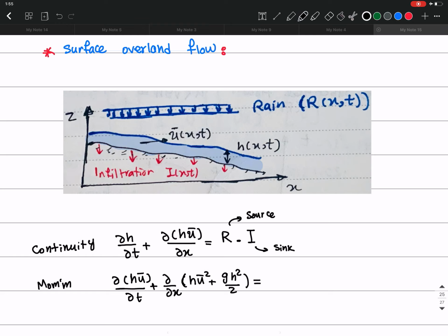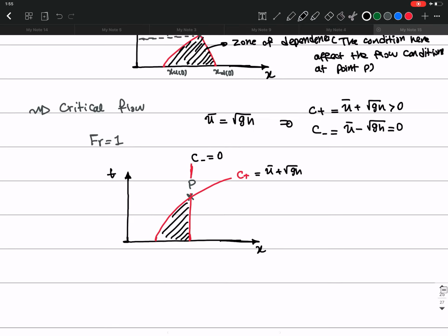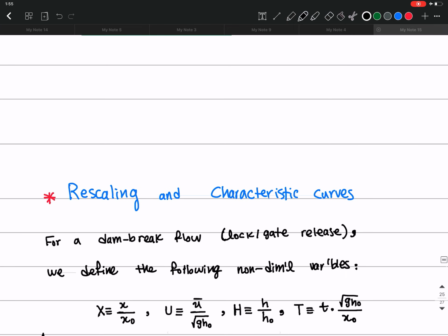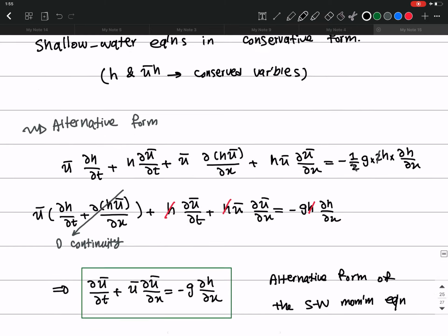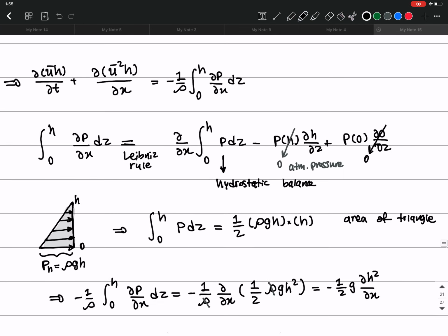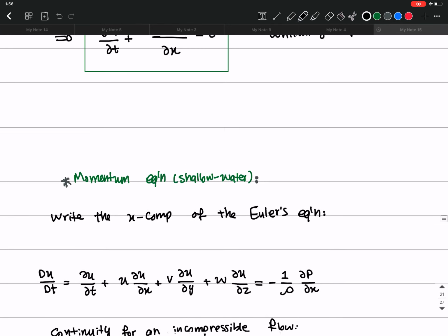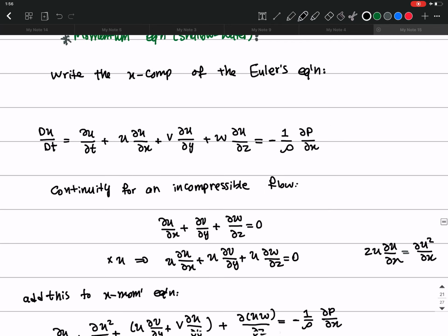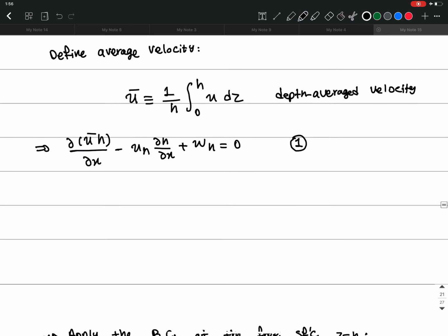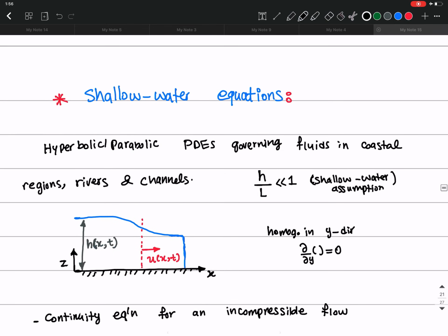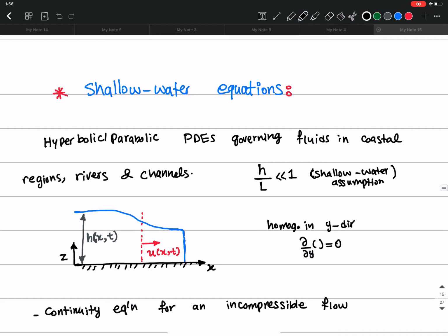if we don't have any viscous forces. And also here, just remember this equation that we derived, this momentum equation, was when we didn't have any gravitational force in the x direction, right? So we assume we don't have any gravitational force in the x direction, like here, because we assume that the flow is moving horizontally, so there is no gravitational force.